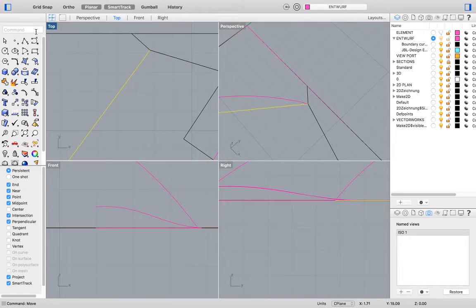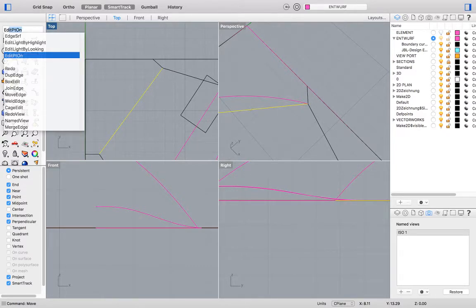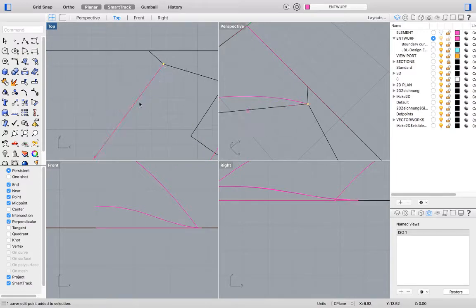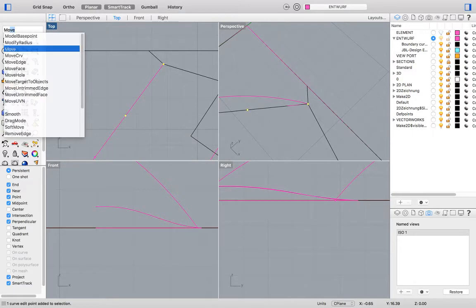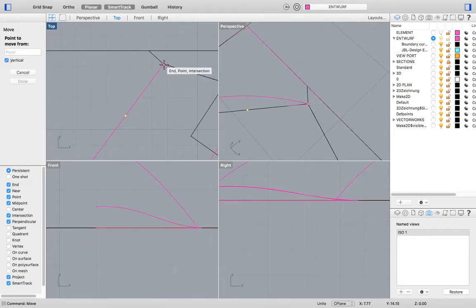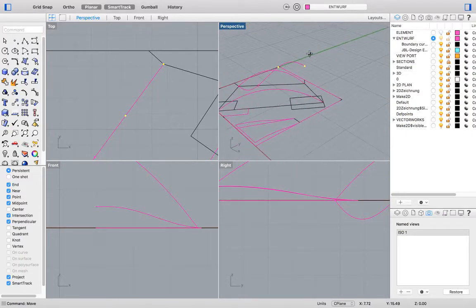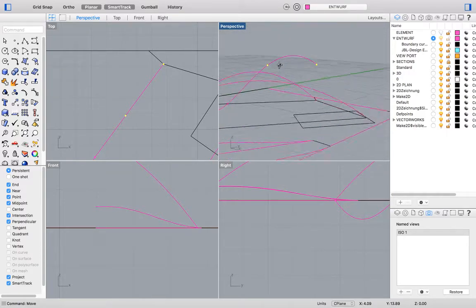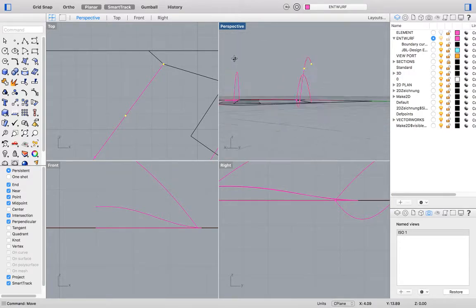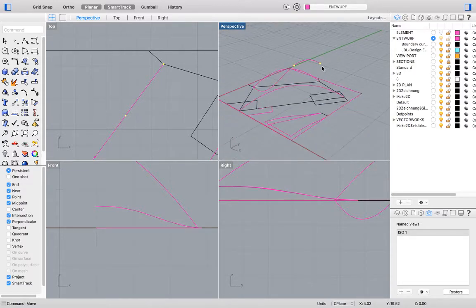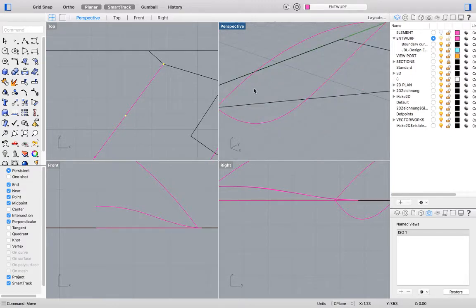and I also need those two curve edit points selected. So edit point on, 1, 2. Let's do that again. Move vertical, point to move from, and point to move to, which we said was 3 meters. So type in 3. There it's made quite a funny curve because of the way the software calculates between the curves between points.